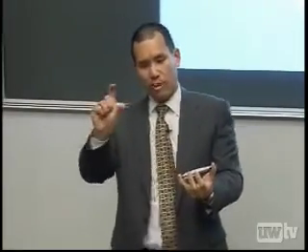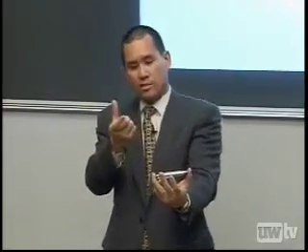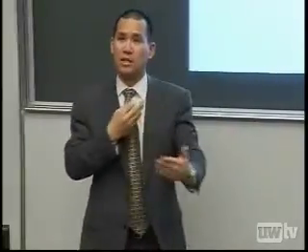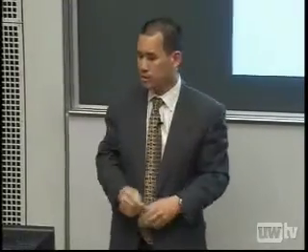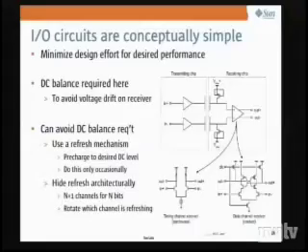What we have measured is that for 25 micron pad sizes, we can get about 8 microns of separation. That's from the edge of the chip face to the other chip face. So once you add the passivation, it's actually more like 12 microns from pad to pad, but that's a reasonable spacing for packaging to get you that close. So we can have this misalignment compensation both in planar and out of plane misalignment. The circuits themselves are relatively simple.